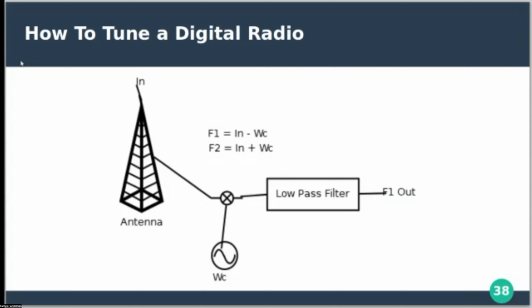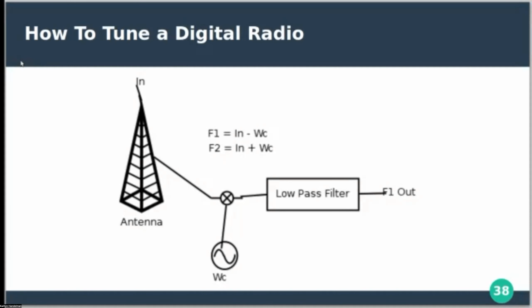And so the way software-defined radios work is that they essentially convert the raw radio waves into something like a stereo audio signal. Essentially, if you take a sine wave or a cosine wave and mix it with any incoming signal, you get two waves out: the difference and the sum of both of the frequencies.